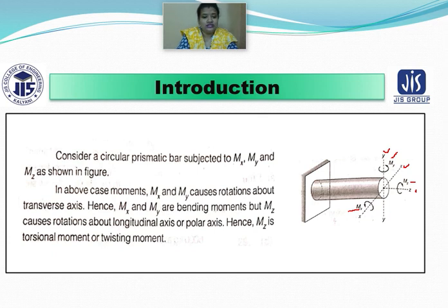Now Jt is your torsion constant for the section you are considering. If you are using a circular rod or a tube with a constant wall thickness, it is equal to the polar moment of inertia of the section.